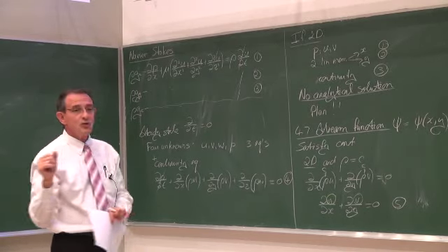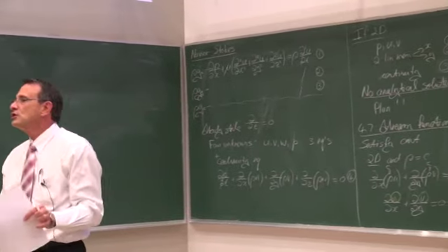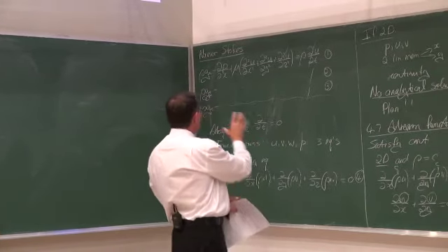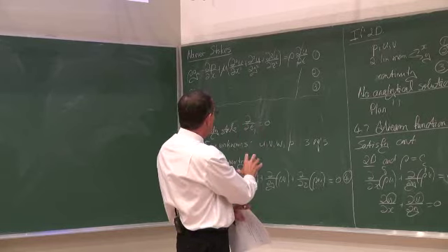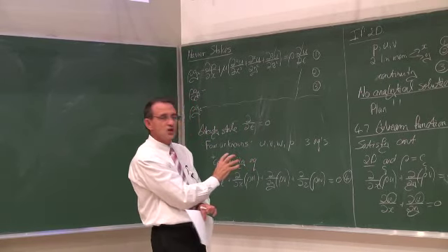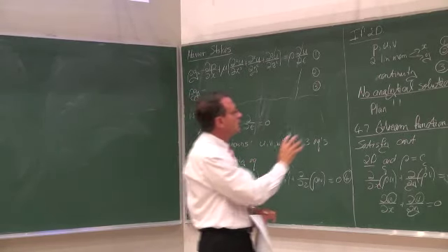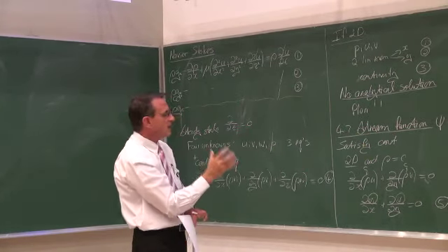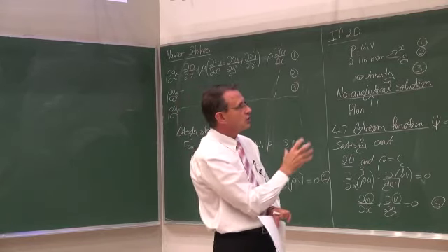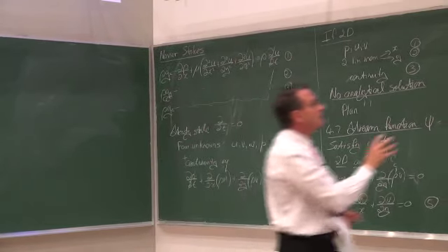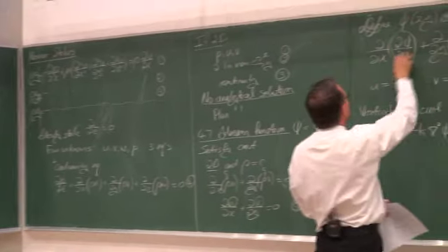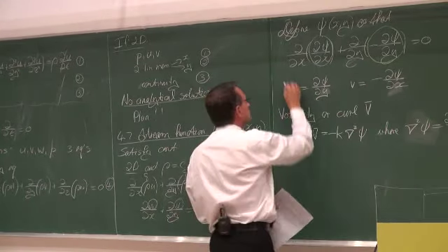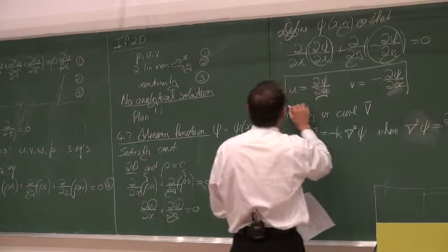We look at the Navier-Stokes equations and we cannot really solve them. Okay. So we make some assumptions in terms of making it steady state. The density is constant, so it's incompressible. We make it two-dimensional, and now we end up with a continuity equation and the momentum equation. Okay, so it looks a little bit simpler. And then this thing is defined where u is equal to that and v is equal to that. So this is quite important. This you're going to use.